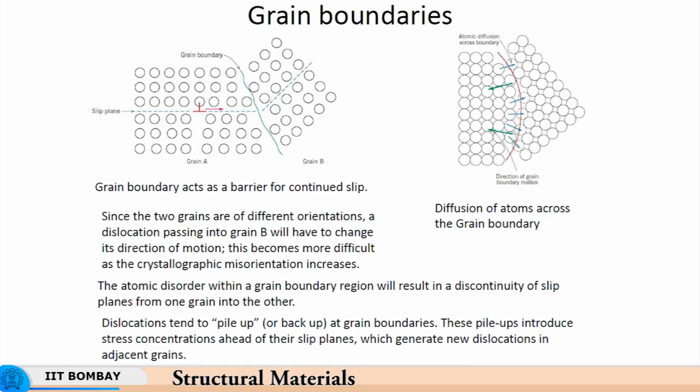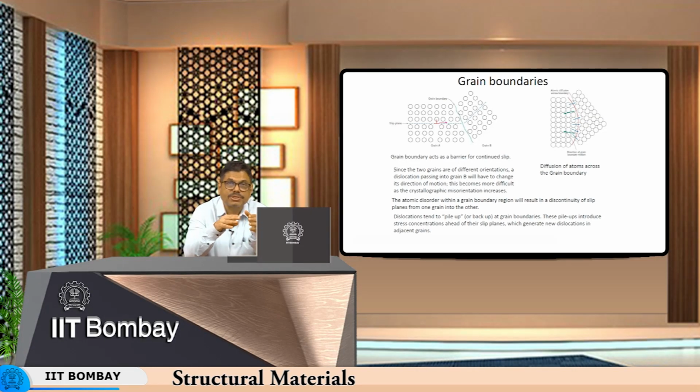Now, if you had too much grain boundary area, if you had lots of grain boundaries here, then there are many regions of weakness, namely the grain boundary at high temperature. The load is high, the temperature is high, and therefore, there is a lot of area in the material that is capable of deforming at much lower stress.